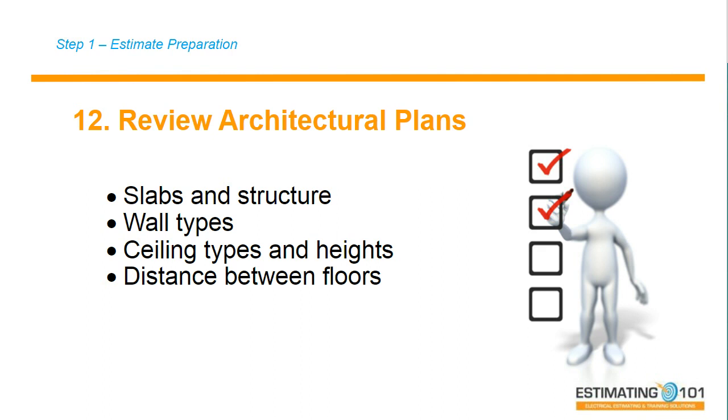Well, I estimated a project one time and didn't study the architecturals close enough, and the project had precast concrete walls that were going to have box outs for all the devices and the equipment connections, and it was very labor intensive in the field for the electricians to stub up and work with the precast concrete and setting these walls. I blew it on my estimate. It is vital that the estimator understand architectural plans and how to interpret them.